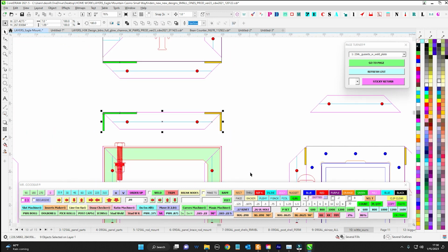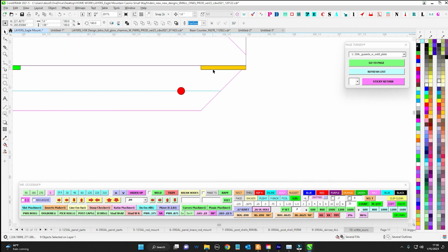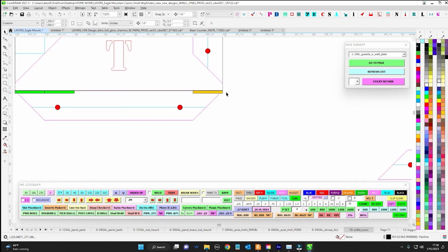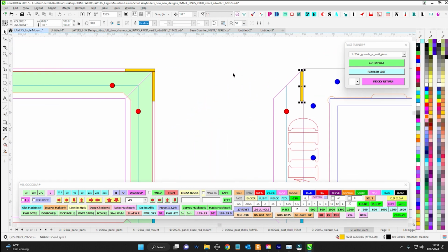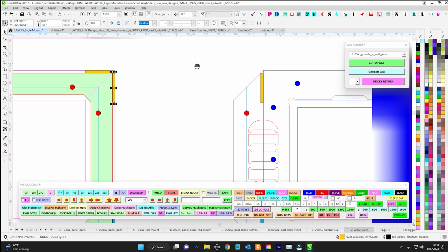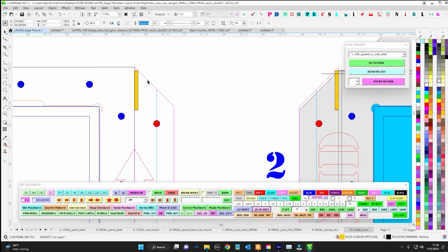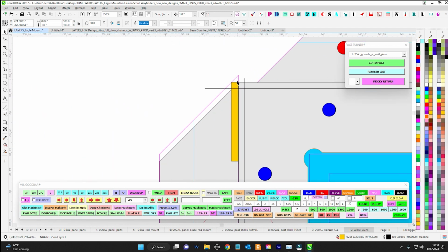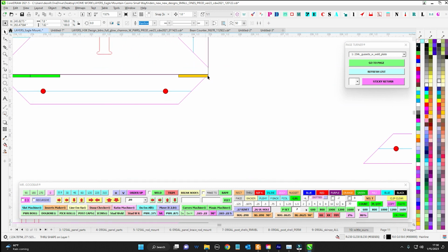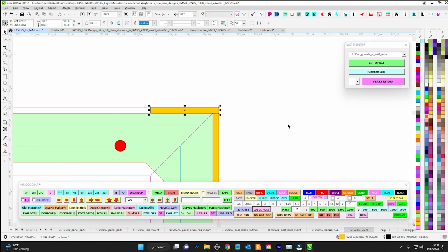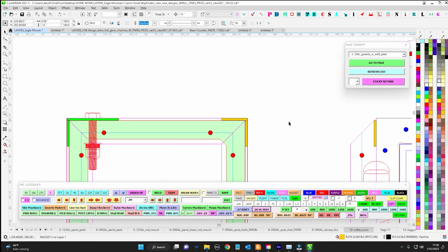And when I make this go up, it now transfers that corner to here. I know that this guy here is long, and this guy here is short. These things are called nuggets, and these nuggets let me know that I'm going to have to shorten. So you can see where I shortened that down to the length of the nugget. And I took that 090 out because this 090 is going to win. So I know that this edge wins, and this edge basically loses. That's how I call it.